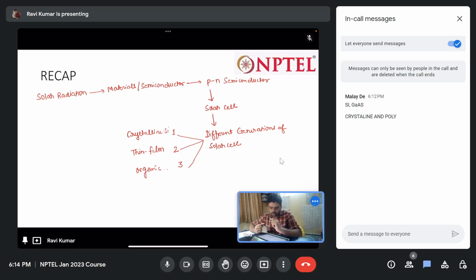So, what kind of module was that? It was polycrystalline. Then how are you sure it was not mono, it was poly? The structure, and it was blue in color. Blue in color is because of ARC, anti-reflective coating, so it will be in all modules.